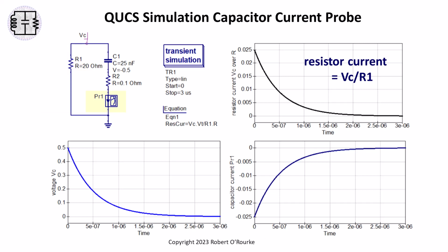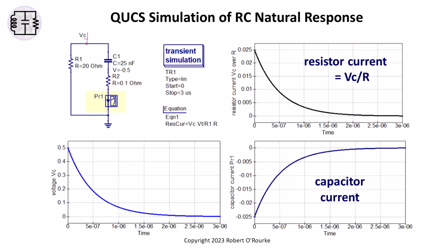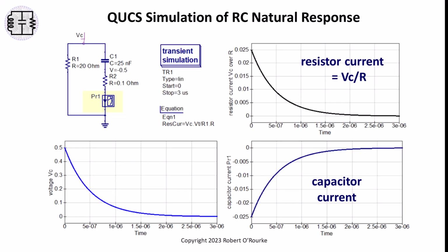The capacitor current is measured by the current probe key R1. The current probe is oriented downward, matching the branch relationship reference polarity current direction of the capacitor. Since the actual current goes up into the capacitor, opposite the current direction of the probe, the capacitor current is negative.